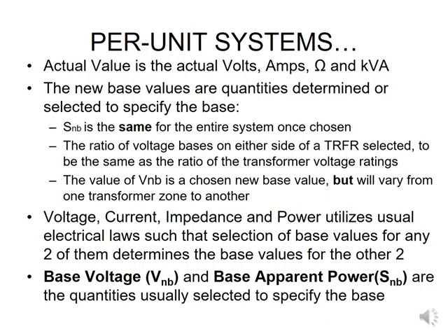So if you've got a line on the 66 kV side of your transformer, you will use the 66 kV as your base voltage for that line. And then if you have a line for the same network on the 11 kV side of that transformer, then you would utilize 11 kV as your base voltage, okay? Because the line is on the 11 kV side.